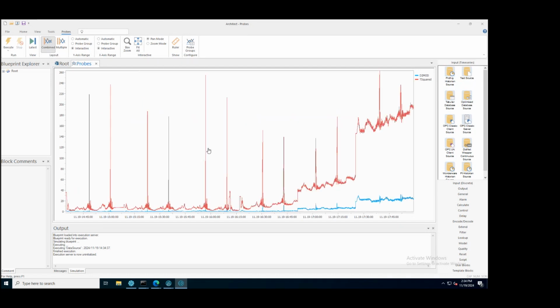And here we can see, well, the first thing we see is that we do have a degradation over time in the t-squared especially, as well as the distance to the model. And we have these peaks, which might be a bit strange. But actually what this is, is when the blade is speeding up and slowing down between different cutting phases, we experience this abnormal or non-linear behavior, right? And that's why it's being highlighted as abnormal. But we're not actually too worried about these peaks.